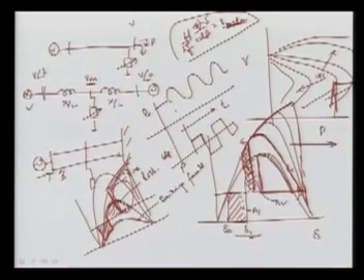What will happen? This machine will be here and slowly this will be stabilized. So with the help of reactive power injection, when it is oscillating and de-oscillating, means power is more or less, then this machine will be stabilized, and this will improve the power system damping, and then we can damp out this.